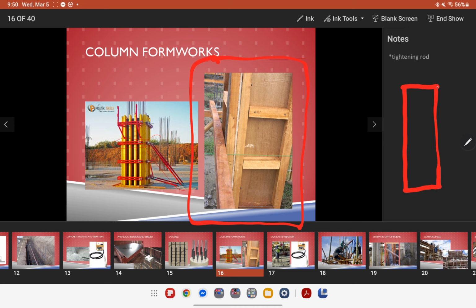These are the vertical studs, while there will be horizontal studs provided also. The spacing for the studs would be around 40 or 0.4 meters apart to make sure that this and this will not bulge once you pour in the concrete.